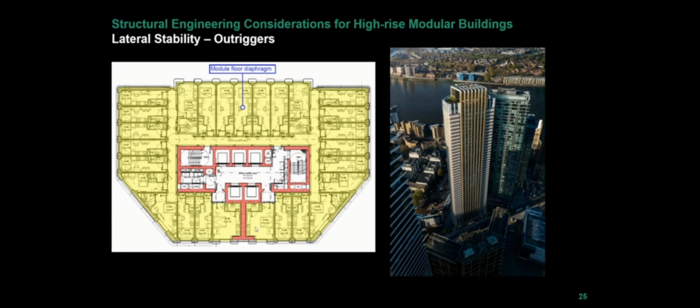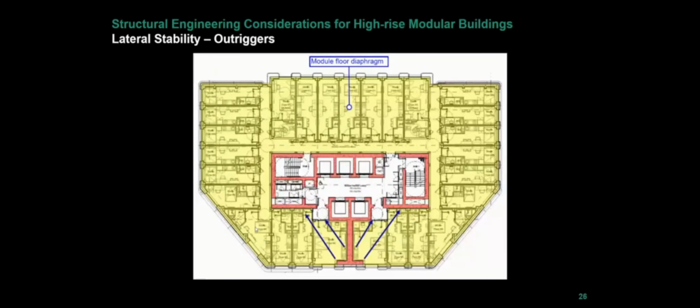So what we did was we introduced a T-shaped kind of hammerhead core wall, as shown there. So you go on to the next slide. In a normal building, that's relatively straightforward because you can rely on, again, out-of-plane buckling of that T. That T takes quite a large compression load when wind blows from the north to the south direction. And you could normally just rely on your concrete slab to resist that out-of-plane buckling with just compression stresses, or axial stresses, into the slabs and back into the main core.